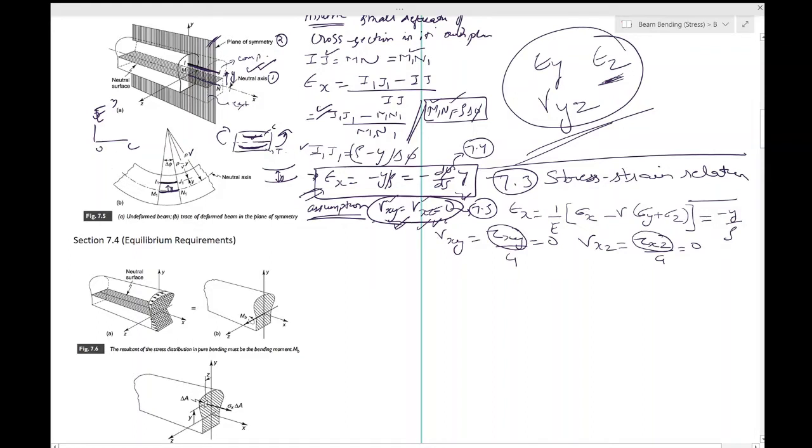Everything is there for pure bending only, when MB is not changing along the length. So the shear stresses are 0. This is something which we learn right away from these discussions, and of course we are inconclusive about many other things, but let's focus on what we know for now. The other gaps will fill later on.